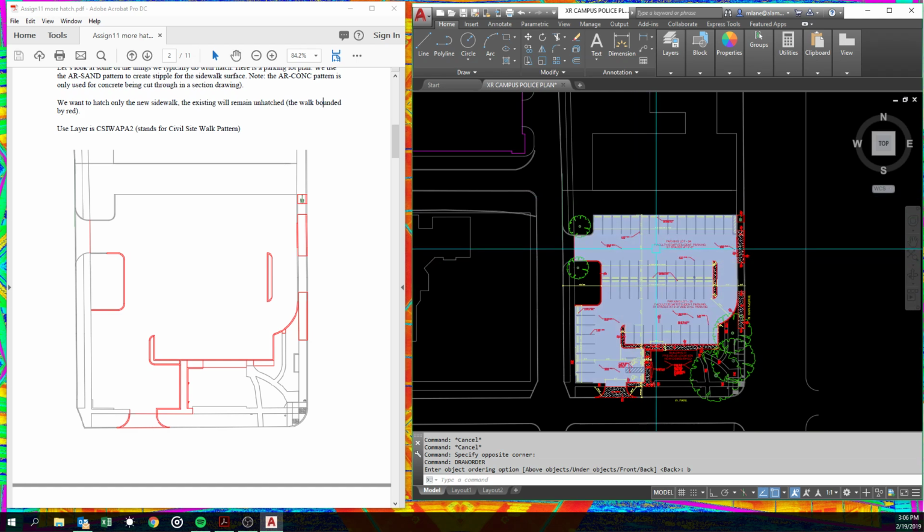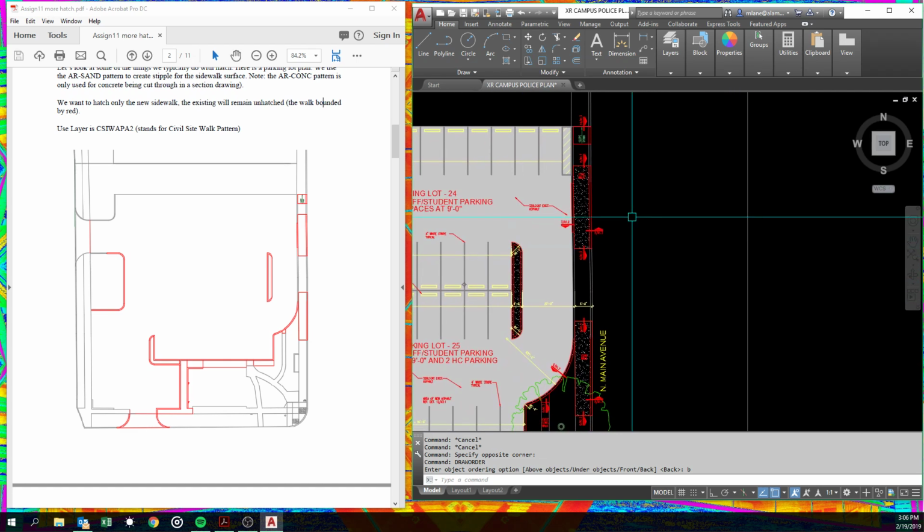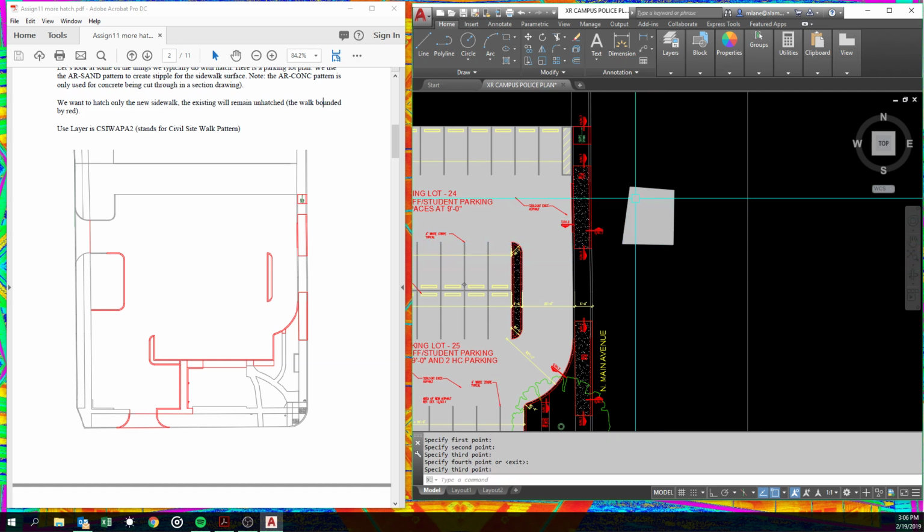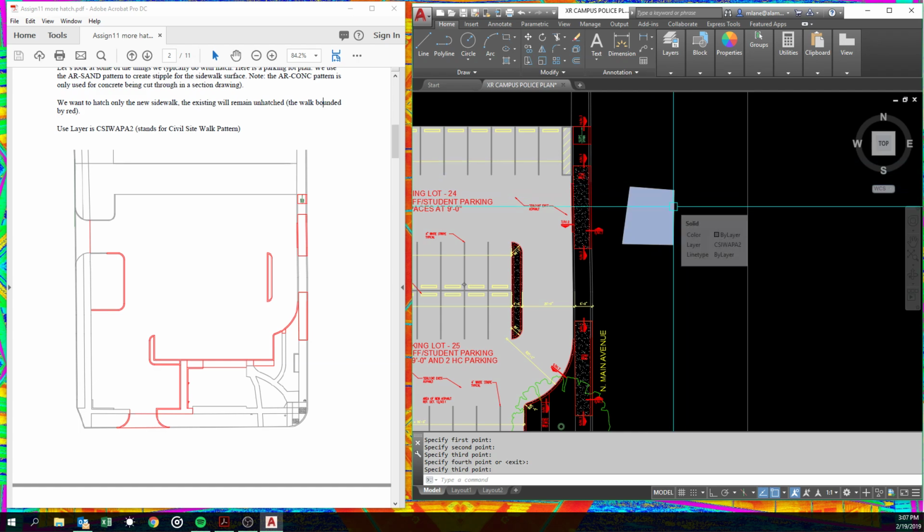There's actually a command to make solids like this. It's not as convenient with all these curves. Command's called solid. This works sometimes if you want it, and you pick your shapes in kind of a Z pattern. The reason is it thinks in terms of triangles, so it thinks in terms of that triangle, and then using those 2 points and this fourth point. Don't ask me. It has to do with how they do some things in 3D. But anyway, sometimes that solid pattern works, but that's a good example of, you'll notice if I move this